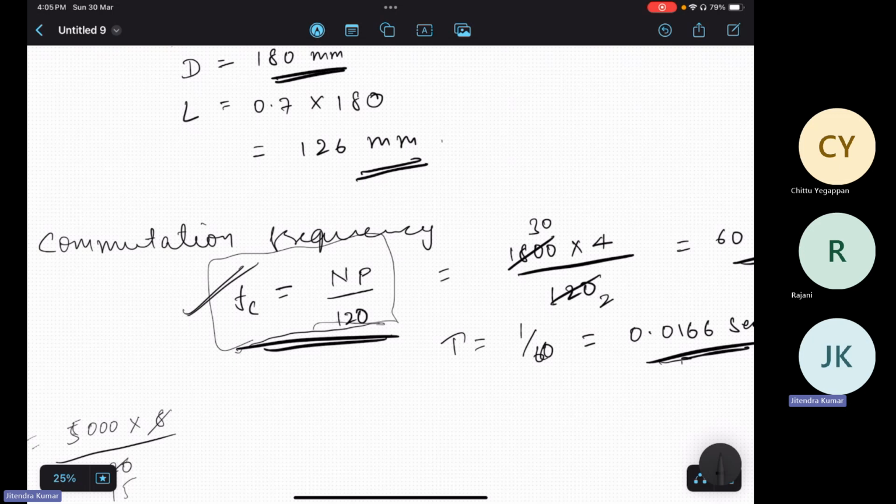Okay. Any other doubt? I was asking about this asymmetric bridge. So you know how many switches are used in asymmetric bridges, right? Yes, sir. In 4-phase SRM, there are two power electronics controlled switches like IGBT or MOSFETs per phase, and two anti-parallel diodes per phase.